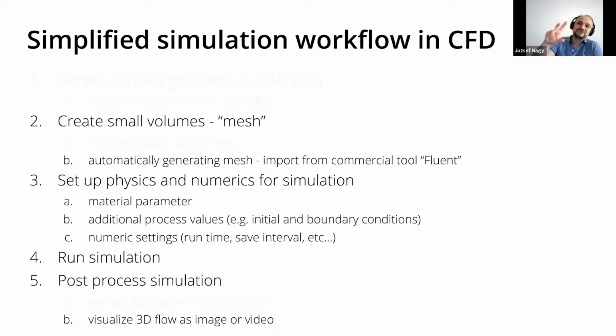So in the 2D simulations, we will not waste any time with the creation of the mesh. I already pre-created the mesh for you. So this is a very special way to deal with OpenFOAM, but a legitimate way. I created years and years ago, when I was young and doing my PhD, a couple of meshes in Fluent, very simple 2D meshes, and we are going to use those for our 2D cases and import them to OpenFOAM format. So we will not worry about meshing. Later on in the 3D case, we will worry a lot about meshing. Here we will import the mesh and then set up the physics, initial and boundary conditions, and then run it and visualize the results.